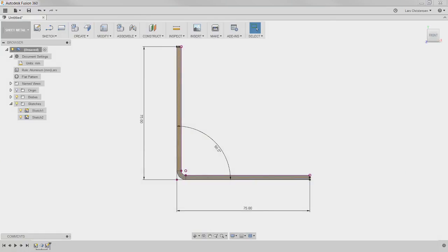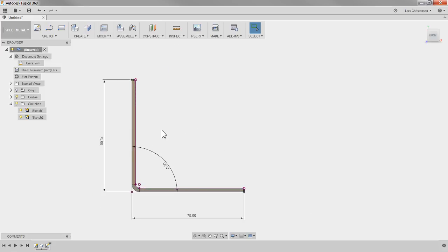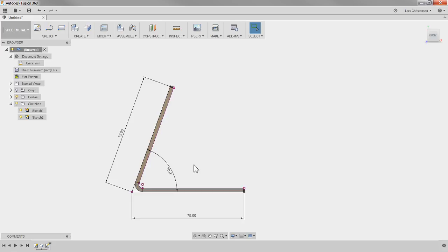What you can do, like I said, is some testing if somebody on your shop floor can't give you K factors. Like I said, some of them already have it. So one way to test this is to go in and take a part like this, and change the angle here from 90 to 70, like this.